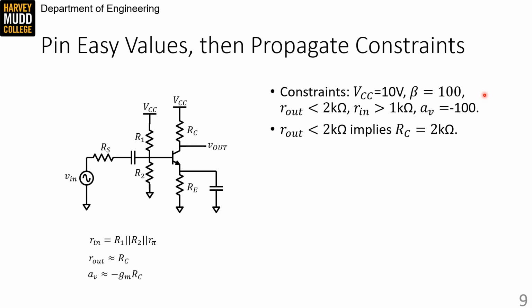It can be tempting to try to leave RC defined by an inequality, maybe in hopes of getting a mathematically perfect value for it later or giving yourself some design freedom down the line, but that will drive you crazy. There are a lot of moving variables in circuit design, and you'll do better if you just pick values for some elements for your first few designs. Trying to keep those inequalities alive longer is a pretty sophisticated design technique that's quite hard.